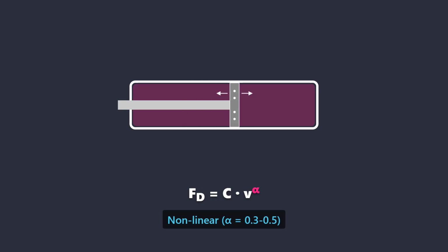This nonlinear behavior provides a high damping force during high-velocity earthquake movements, but offers minimal resistance during slow movements, such as wind loading. Energy dissipation occurs as the viscous fluid is forced through small internal orifices, converting the kinetic energy into heat.